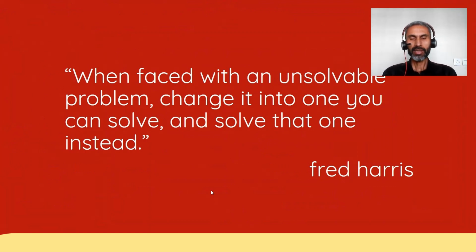From intuition, we should estimate the range of a target through the time delay. We emit a waveform and we record the time of arrival of the signal back to the receiver. And from there, we can estimate the range. But we will see that this method is less accurate and more expensive. And instead, we can change this problem into estimating the frequency of a sinusoid, which is much simpler and more accurate to do. There is another application of this principle that we will see within the presentation itself.